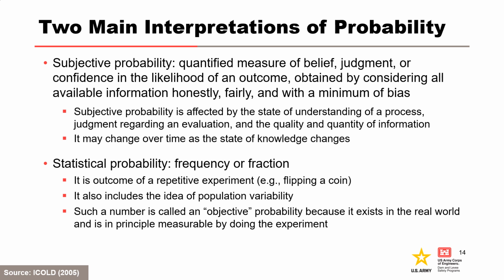This change in knowledge could be the result of subsurface investigations and drilling, or material testing. It could also be the result of performance observations. Perhaps an embankment is loaded by a stage it has never experienced before, and seepage is observed. Or perhaps seepage becomes turbid, or its volume increases. These observations can obviously change the probability we might estimate for a given event.